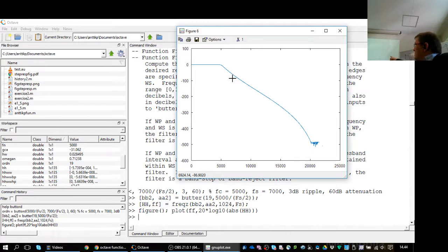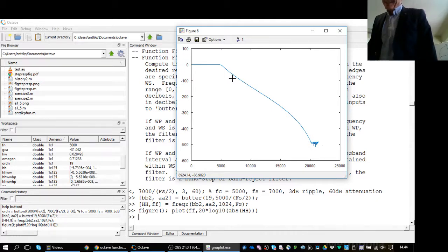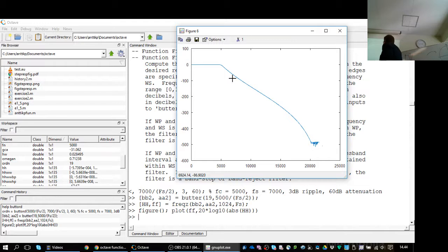It doesn't matter if that goes practically to infinity. See, minus 500 dB is a lot. Actually, look at that one. It hit the floating point accuracy level here. So machine epsilon is found. In reality that will go to 0, which means infinite decibels there. But anyways, that's what happens when you warp the frequency scale by grabbing from infinity and minus infinity. But anyways, this is the way to design a low-pass Butterworth filter.